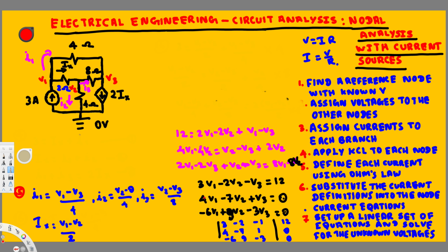So now the idea is we take the determinant. If you want to find v1, what you do is take the determinant, and for v1 we know that the first column is v1. So we swap the constants column with the first column in order to find v1. Whatever you are trying to find, you have to swap with that.